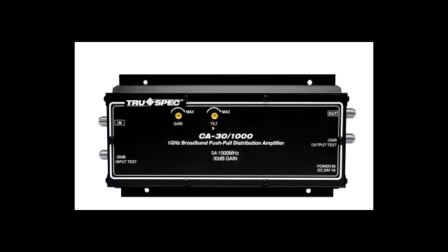However, some of the higher frequencies are going to come a little bit weaker. So you're going to see a weak signal on the TV, right? The further away you go from the amplifier. So what happens is that you need to adjust, because that's a naturally occurring slope. Okay. So in order to compensate for that, you are going to adjust the slope on the amplifier, and in this case, the slope is labeled as tilt.